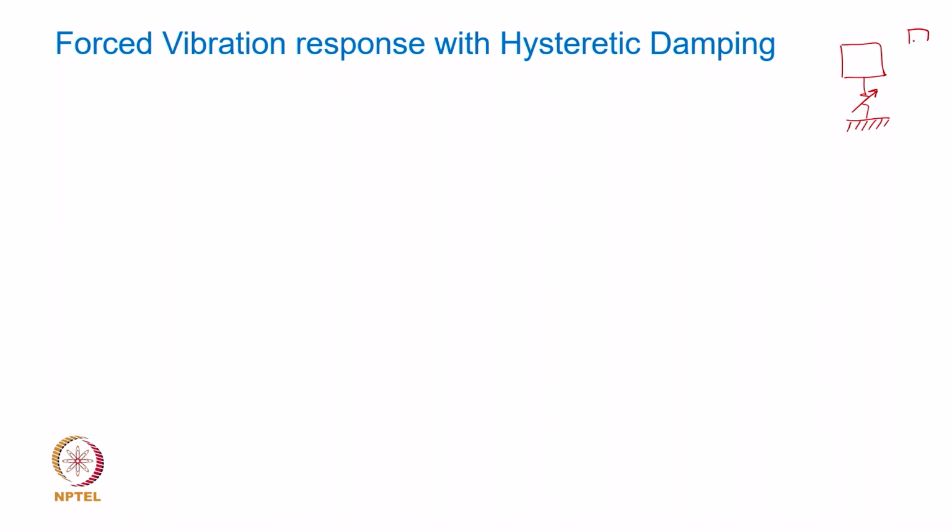We discussed that it can be both stiffness and damping property in one single structural element, that is the engine mount or any rubber isolator, polymeric isolator, or even a simple structure, let us say an I beam or whatever is the material. So, the only difference in this case, we have discussed this, is that it has a complex stiffness. You remember K was actually a complex stiffness.